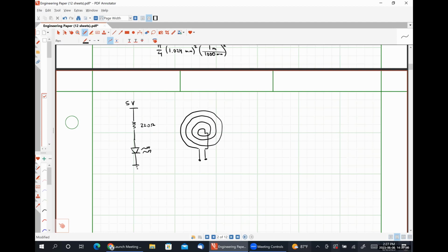Yeah, so a space heater, the heating element is just really a section of what's called nichrome wire. It's a really thin wire that can handle a lot of current before it melts. And so you take this really thin wire and you wrap it around all over the place numerous times, pass a current through it, it starts glowing red hot but doesn't melt, and then you use a fan to blow the heat off of the wire, and that's how you heat your room.